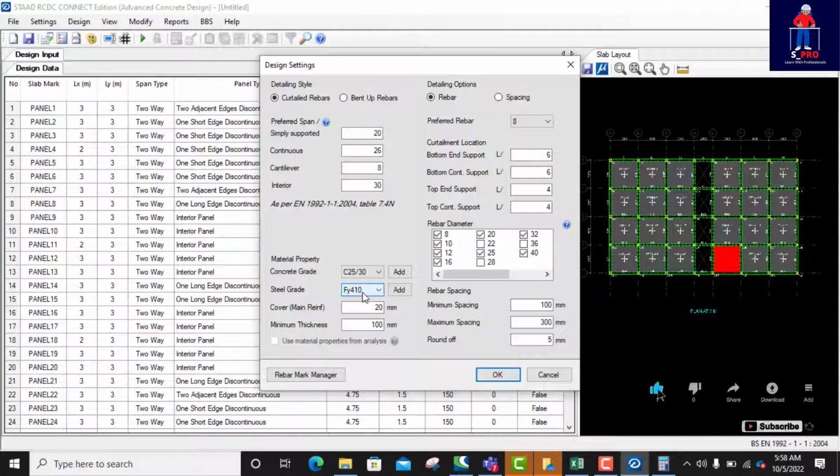during production, you cannot be very sure that the strength will come out to be like 500. So for you to be safe with your design, you have to choose a lower value. So that's why 410 is conventional. People normally use 410. So even if after fabrication or production of steel members the strength is not up to 500, I don't think it can be as bad as 410. So that's why people use 410 for their steel design.